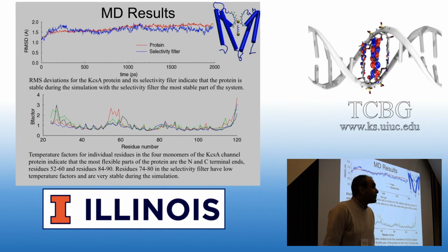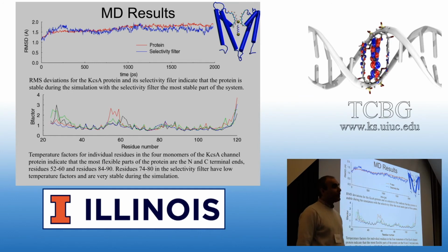Anything else? Yes. Okay. So in the giant whole cell simulations, you described a very thorough method for placing proteins in the membrane. And whenever I've done membrane simulations, I simply put the protein in and then delete lipids that are within a certain number of angstroms from the protein, and then equilibrate that. So is that an improper way of doing it? No. You're fine. This is not a problem if you have a single copy of the protein, a flat membrane, things can shrink easily.